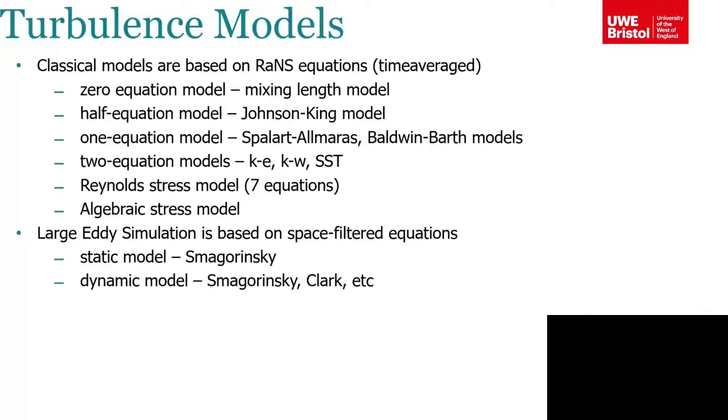Yeah, because you have a large variation in the area, the flow can become turbulent at certain parts. That's the tendency. So there is no harm in using a turbulence model. If the flow is laminar, it will be laminar anyway. When you use the turbulence model, it doesn't mean that it's going to assume everything is turbulent and not show you when it's laminar. No. If it is laminar, it will still be laminar with the model.